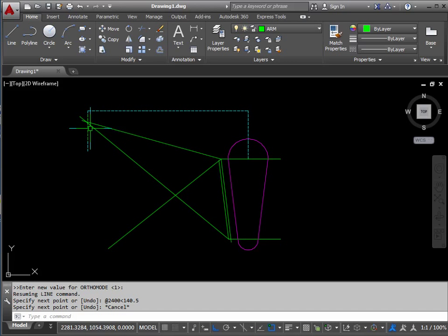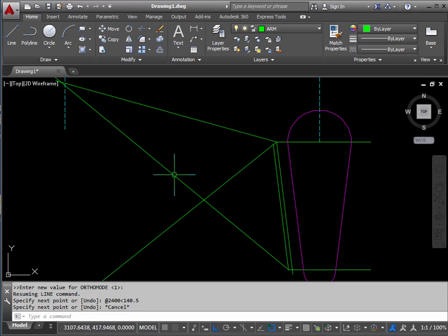and it really is shaping up now. There's lots of tidying up to do here. We need to give these elements their thickness, the same with this chord here, and to tidy up the end. So let's establish the thickness of the structure first. Okay, we'll offset this line in by 30, offset this line in by 30, but this is the middle of a piece of metal, so this one's going to go 15 this way, 15 that way. So the offset command is here.